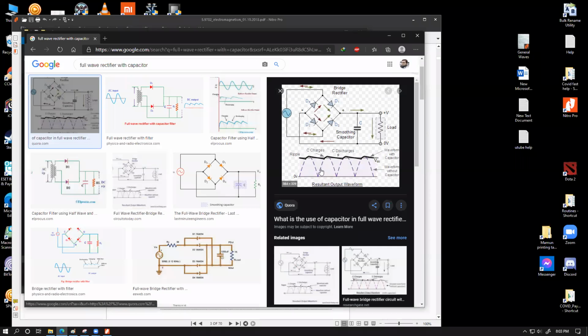So this is the scenario. With the full bridge rectifier, without the presence of the capacitor, the output voltage would be these purple lines. Whenever we introduce the capacitor, when the supply voltage goes up from here to here, the capacitor charges itself, and for this duration the supply also runs the load. In this case, the capacitor is charging, so capacitor is absorbing energy, not giving out energy. When the supply voltage starts to drop from its peak value, capacitor is now at a higher voltage. Capacitor cannot drain to the supply, so the capacitor will now start to feed the load.